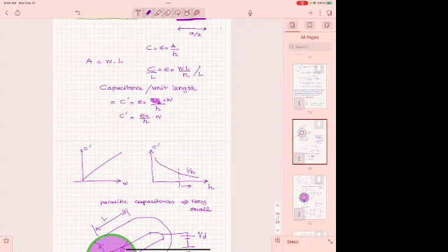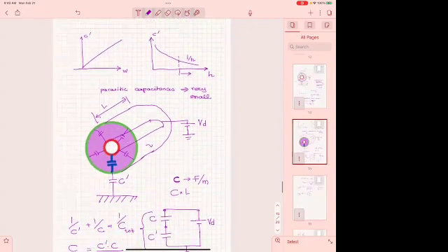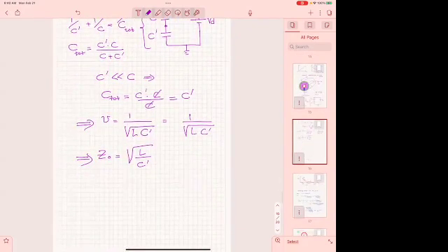Yeah, it could be appreciable. Yes, it could be significant, but these entities that I showed you, V and Z naught, have L and C prime, which are per unit length. Practically, one is in H, Henrys, the other is F, farads. Henrys times farads gives a second squared. So this is going to give you meters per second, which is velocity units.